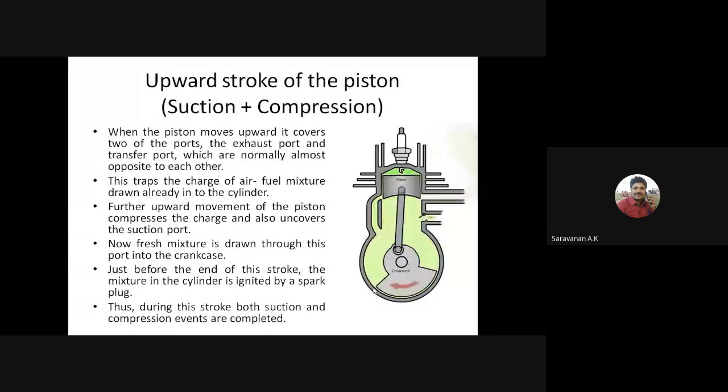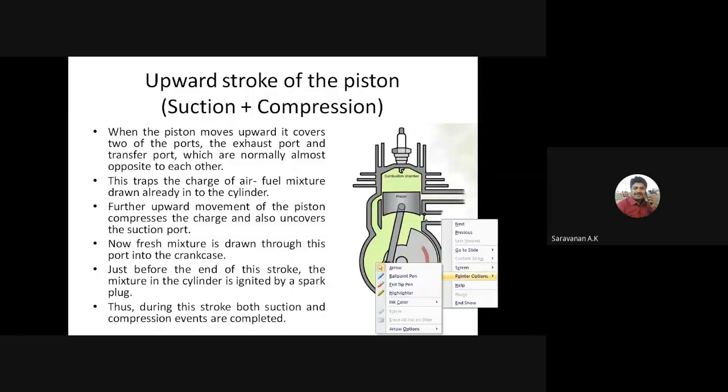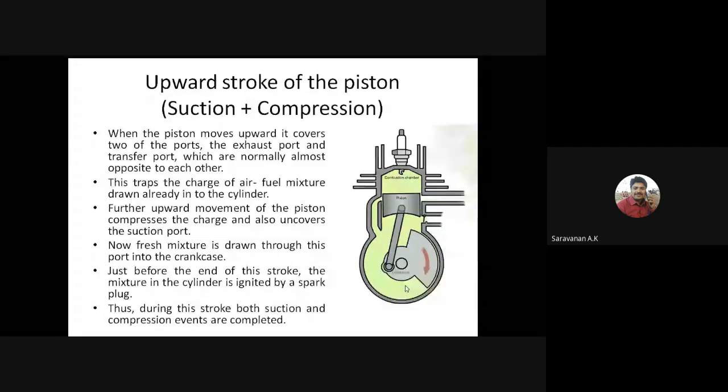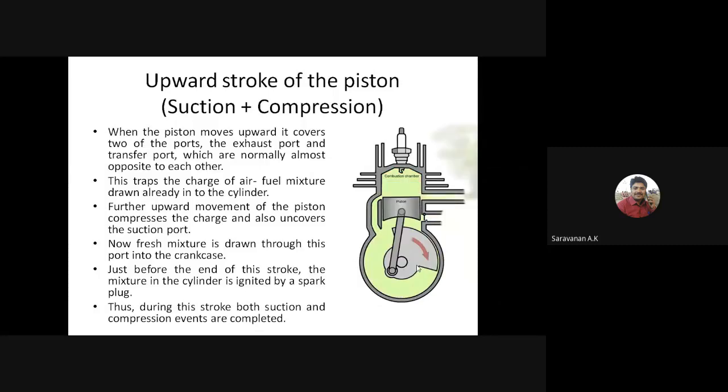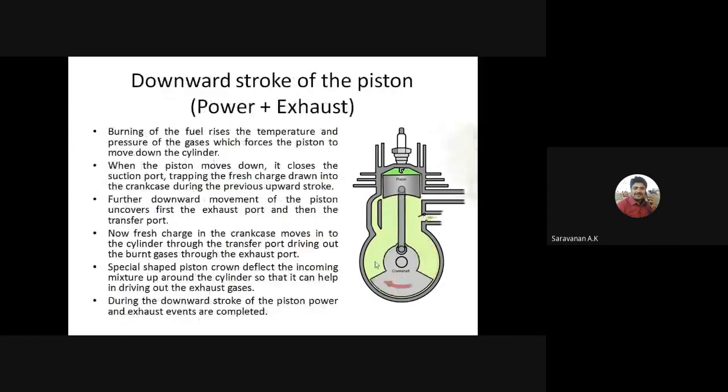Here is how the crankcase is arranged. In the two-stroke engine, we get an inlet, which is opened from this charge. You may see the inlet passing through this chamber, where the air and fuel will be mixed in the crankcase.